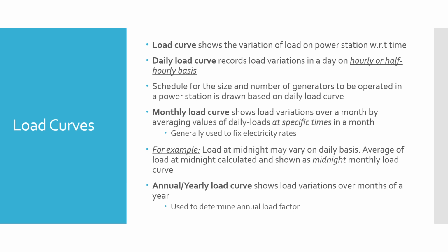The annual or yearly load curve shows the load variations over the months of the year. Normally this annual load curve is used to determine the annual load factor, and I have included some exercises as well to give you a taste of how this is done.